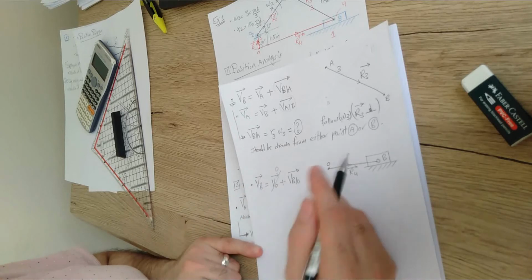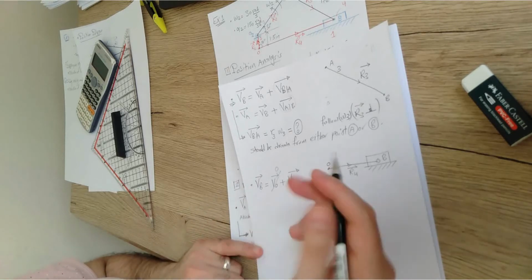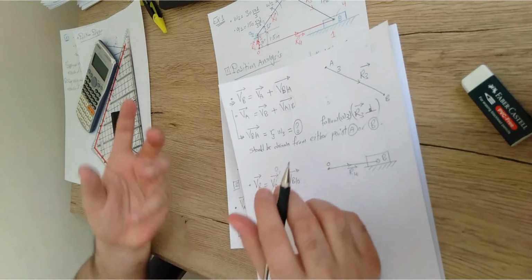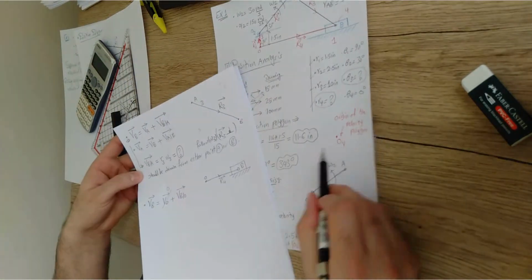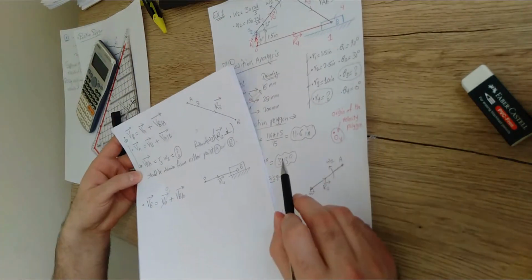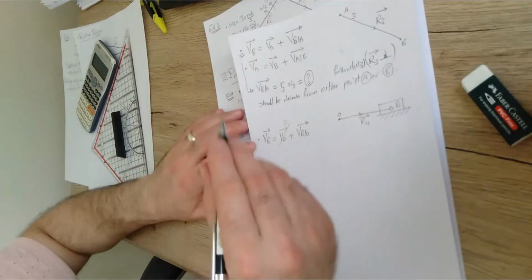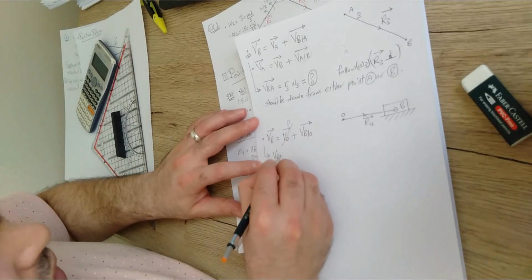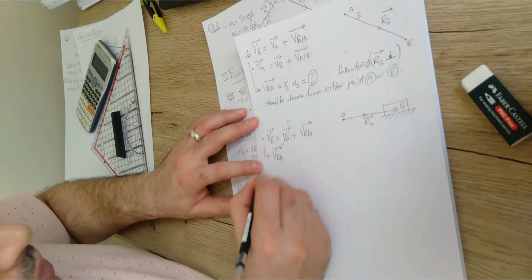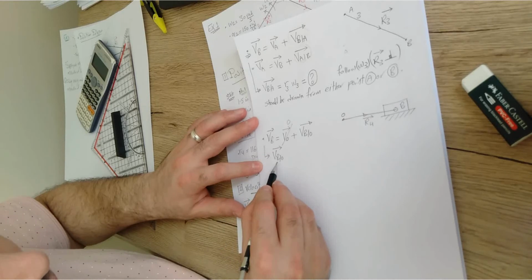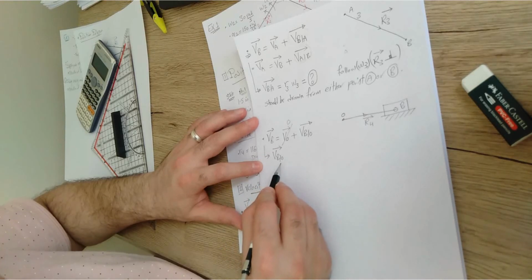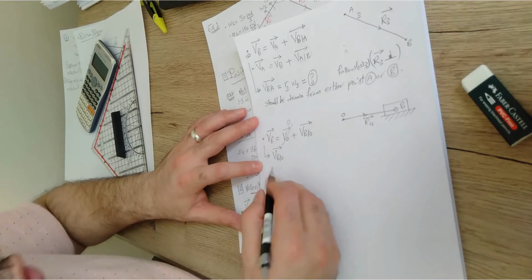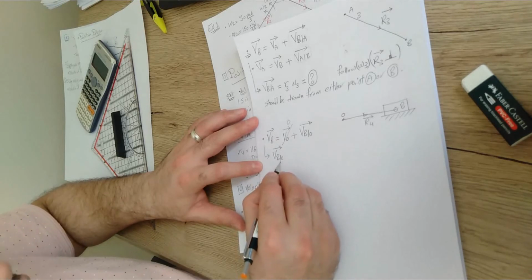It means that in the velocity diagram, point O will be considered the original point OV. Make sense? As I'm going to show you, for this one, we are just going to draw the VB relative to O vector. It would be drawn from either point B or point O. Definitely, we're going to have point O, because point O has zero velocity, so it will be drawn from point O.